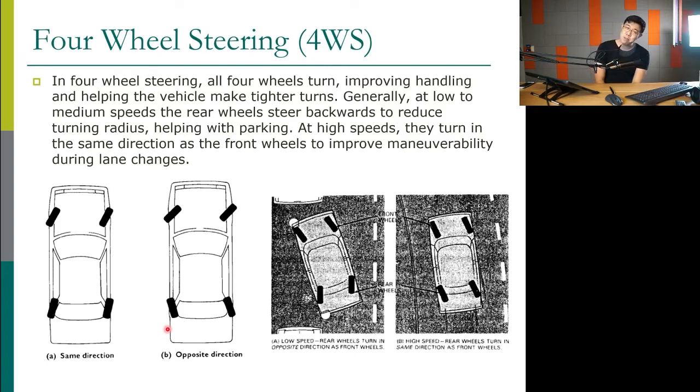This motion is something the passenger can detect. It might be nicer if the car can just slide to another lane, instead of turning to another lane like this. Would it be better if it can slide to the next lane? It will be quicker and create less angular movement, which means it will be safer and nicer to ride in the car, right? But if you want to do that, the rear wheel has to turn also, so it will improve when you change lanes. So that's one reason.